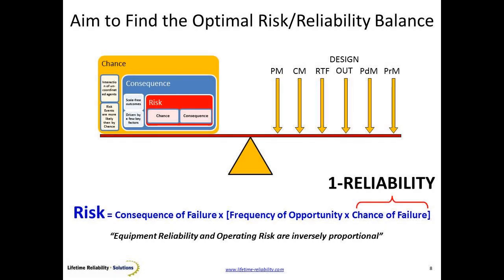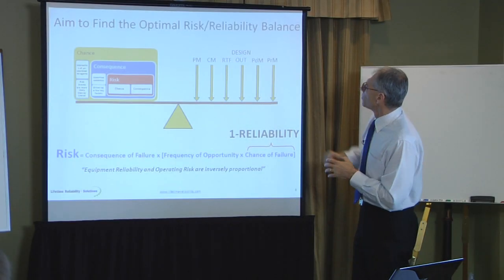In the end, as a business, as an organisation, there isn't a lot of things we can do. Certainly when it comes to maintenance of machines to prevent breakdowns and to minimise risk, there's only a few strategies we've actually got available. Preventative maintenance, corrective maintenance. So we detect something is not right, and if we don't correct it, it will lead to a failure. So we actually stop the machine and correct the problem. Run to failure maintenance. So we'll accept a breakdown and simply repair it when it breaks. This you might use if you have a standby unit. You've got a standby, let the duty unit fail, start the standby and repair the duty unit on a breakdown basis. Design out the problem.